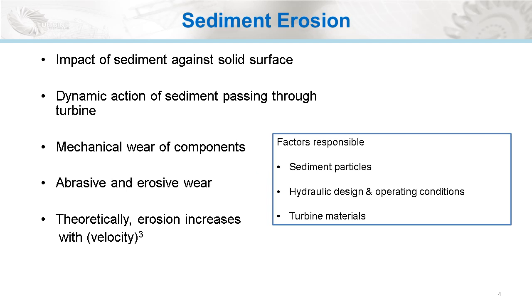Sediment erosion is the dynamic action of sediment flowing along with water impacting against the solid surface. While talking about the sediment erosion, there are abrasive and erosive erosion, which are one of the major problems for hydropower plants operating in sediment water.